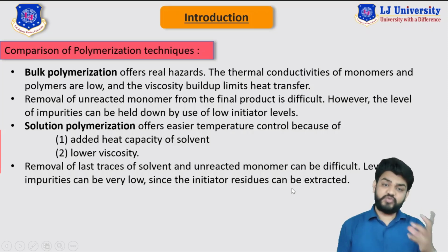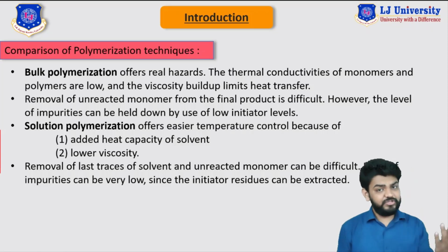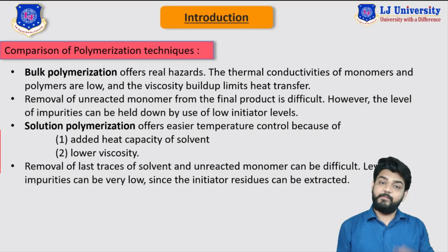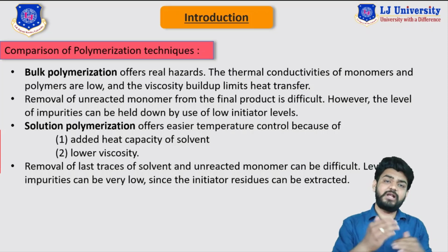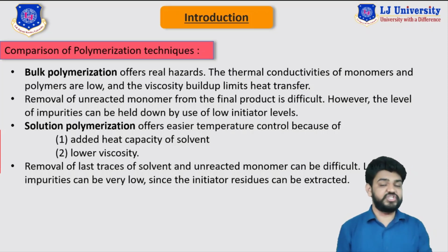So, in the case of solution polymerization, similar to the bulk polymerization, we will have polymer of higher purity. Since we are not using any kind of additives and any kind of other materials, this purity can be increased by manufacturers by using this solution polymerization. In fact, the unconverted initiators can also be easily extracted out from the entire reaction mass. So this was the small comparison between this bulk polymerization and the solution polymerization.